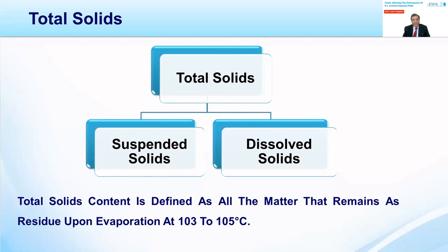If you go through the data sheets of the membrane which you are using in the RO plant, or the UF or the NF or the MF membranes, you will see the whole data sheet has given the feed water conditions which must be followed, and they also give the tolerance of the temperature and the pH range that should be maintained. Once we maintain those conditions, we can enhance the life of the membrane and the system, and consequently the operating cost will decrease, as the cleaning frequency of the membrane decreases.